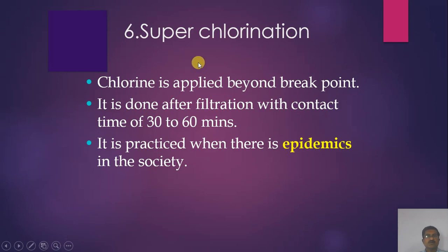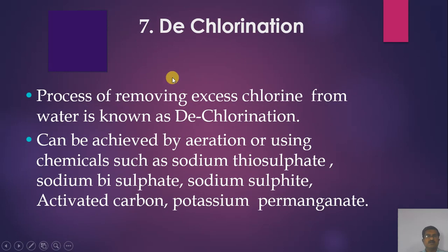Next one is superchlorination. Chlorine is applied beyond breakpoint. It is done after filtration with a contact time of 30 to 60 minutes. It is practiced when there is an epidemic in the society. Dechlorination: the process of removing excess chlorine from water is known as dechlorination. It can be achieved by aeration or using chemicals such as sodium thiosulfate, sodium bisulfite, sodium sulfite, activated carbon, potassium permanganate, etc.